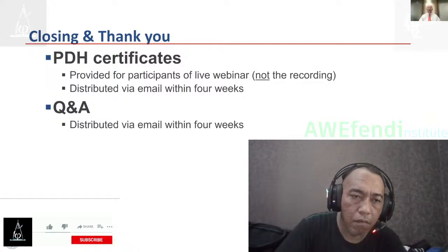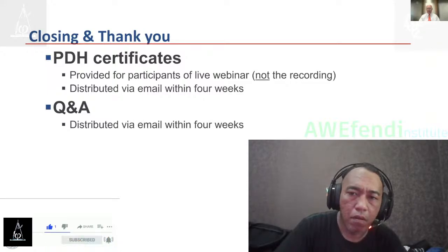Yes. Yeah, and it's a question I run into all the time. So the answer is yes. We are normalizing those displacements. So the TIR is delta max over delta average. And so it doesn't matter if the delta max is 1 inch or 1/4 of an inch. If its relationship to the average satisfies that trigger, there is twisting in the system. I will say that it's a mathematical reality that there is twist in the system.